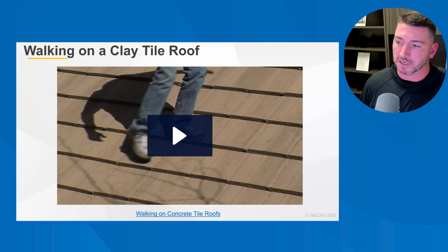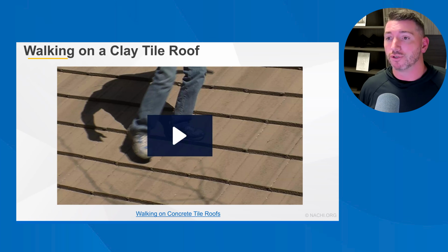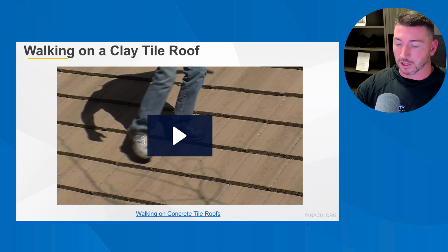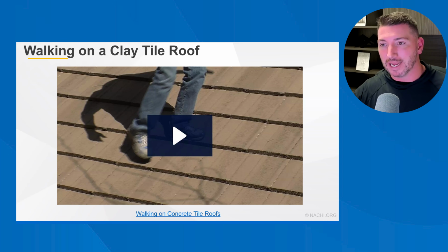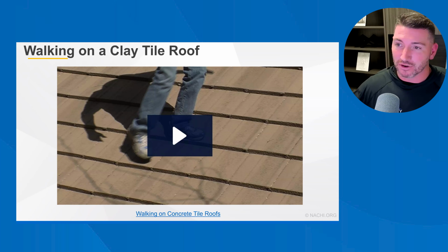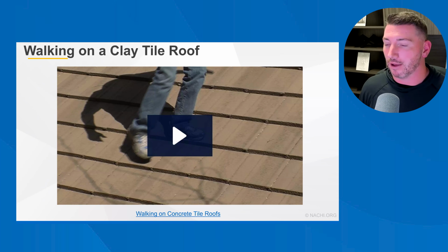And so when you step on a hard material like this, especially cedar shakes, but concrete tiles also, clay tiles, I mean, clay tiles are very, very difficult to navigate without breaking. So use common sense. But the concrete tiles that he's walking on, you would think, man, concrete, that's what the sidewalk's made out of, so I should be fine. If you don't walk on that lower third, that headlap, as you walk, you're going to hear a crack. And that sweet, easy to walk on concrete tile now becomes a surfboard to take you right off the roof. So that's basically what he's communicating: how do you walk on these roofs? You need to walk on the headlaps if you're even going to walk up there.